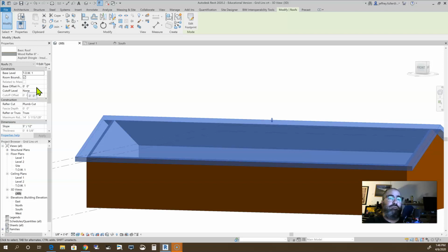Or if you wanted it to be a negative number, maybe you want it to bring the height of those walls down just a tad with your roof, and you can do that. You can just type in a negative, say a negative 0.2 inches, and then it would actually be a little bit below that top of wall 1 level.